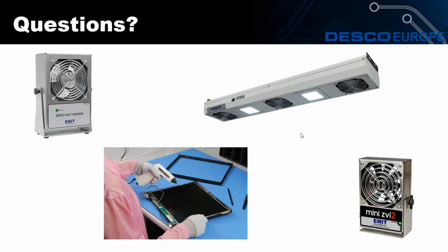What do I mean by that? Different environments are going to have different levels of dust in the atmosphere, and because we're talking about high voltage emitter points, they are going to attract that dust out of the atmosphere and affect the performance of the ionizer. In a dustier atmosphere, your ionizers are going to become less effective more quickly, so you're going to need a shorter cycle of testing and validation.